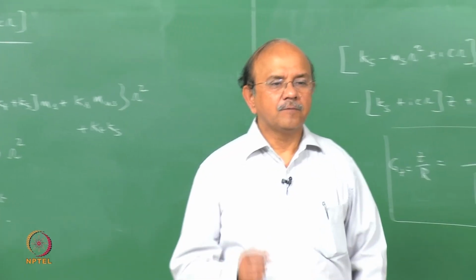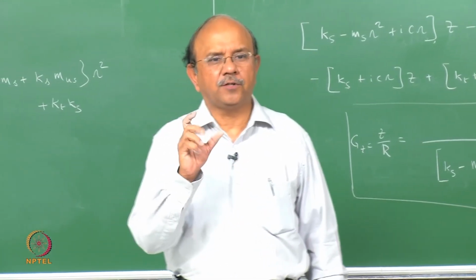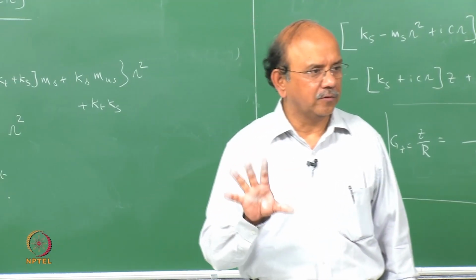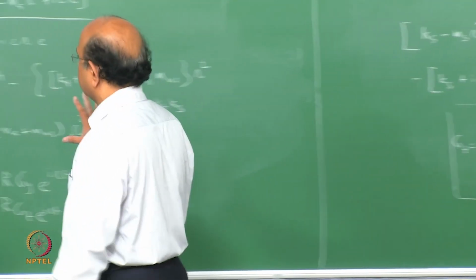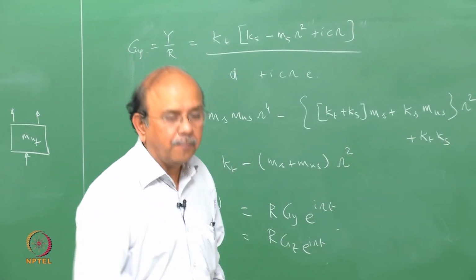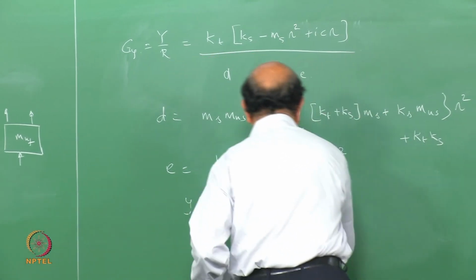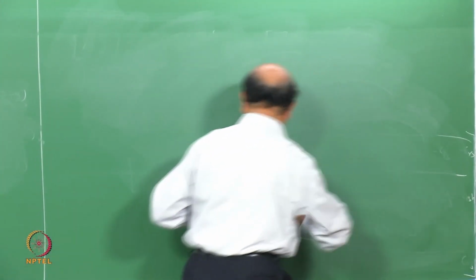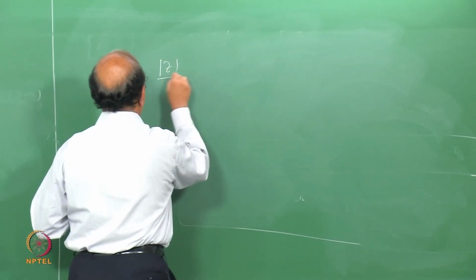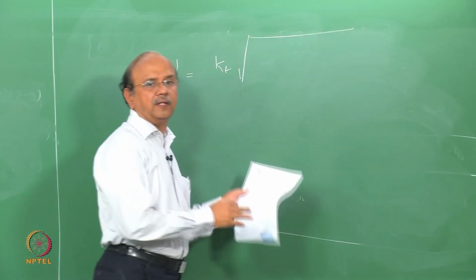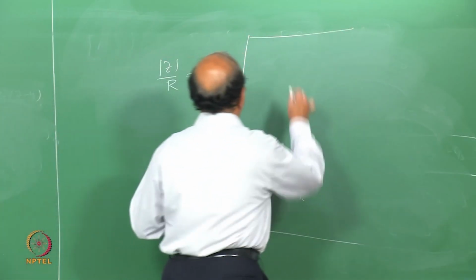as well as you can do it by a quarter car model. We're going to give a small twist to this. Is it exactly acceleration? Is it something else? We'll come to that. We'll give a small twist to it. But nevertheless, from here, what we are interested in is the acceleration, right? If you want the magnitudes of Z and R, we will finish this class with that. Magnitudes of Z and R. Of course, you know how to get the magnitude, the root of real squared plus imaginary squared.